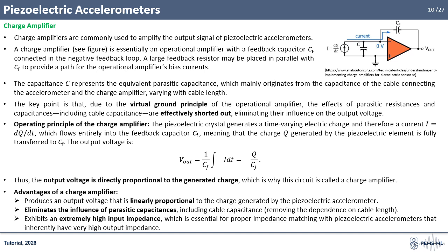It provides an output voltage linearly proportional to the generated charge, eliminates the influence of parasitic capacitances and resistances, including cable capacitance, and offers extremely high input impedance, which is essential for proper matching with the high output impedance of piezoelectric accelerometers.